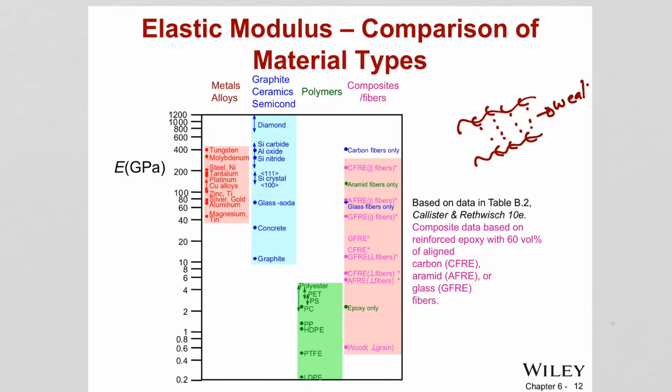So when we try to deform the material, actually these weak bonds are broken, not the carbon bonds. That's why you might expect polymers, because of these carbon bonds, to have a very high modulus, but in reality they have the lowest modulus compared to other materials, because these weak bonds are determining the mechanical properties of polymers. So the chains can easily flow over each other, and the material can easily deform.